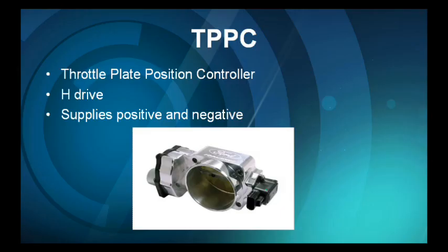Now, after you've either cleaned or replaced the throttle body, you need to look into your scan tool and see if you have any type of idle relearn procedures and system tests. If you don't find any reset procedures or idle relearn procedures in your scan tool, I always let the engine run in park, a hot engine, let it run in drive, a hot engine, and let it run for a while hot with the engine idling, with the air conditioning on.